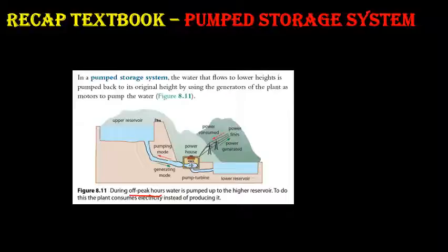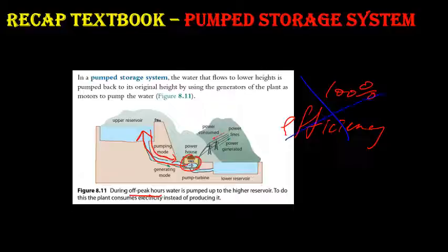What they do is, after they get the electricity, they use a pump to pump water up to an upper reservoir. When they need the electricity, they release the valve here and let the water flow down again to generate electricity. This is the idea, but pay attention that there's no 100% efficient system in the world. So you may not always want to do it, because you usually lose some energy in the process, which is transferred to waste energy.